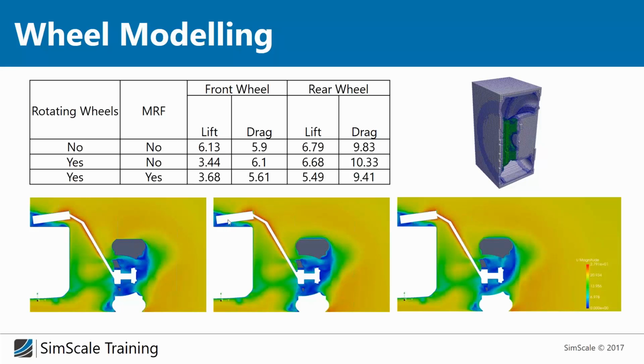Pankaj wants to know how fine the mesh needs to be for DNS simulation and how to calculate the length scales of the smallest eddies. First of all, the fineness of the mesh for DNS depends on the Reynolds number, but it's really, really small. For a simple airfoil, let's say, we will talk about micrometers of edge lengths. Therefore, DNS is not an option. Even big Formula 1 teams cannot do DNS for a full car. It's just not possible.